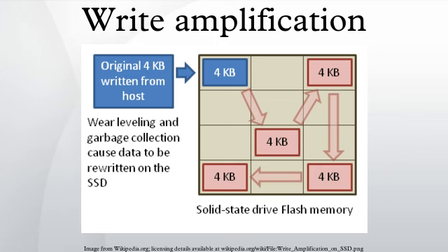Background garbage collection. The process of garbage collection involves reading and rewriting data to the flash memory. This means that a new write from the host will first require a read of the whole block, a write of the parts of the block which still include valid data, and then a write of the new data. This can significantly reduce the performance of the system.